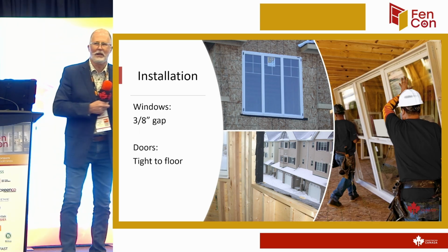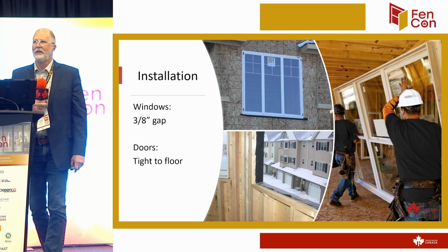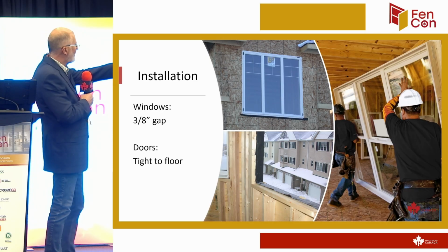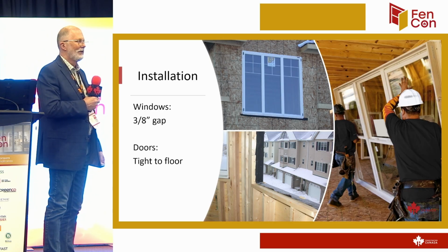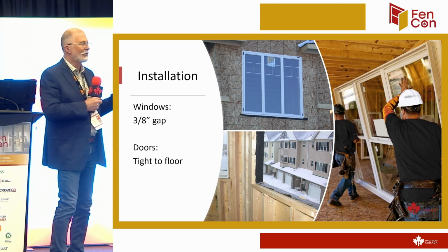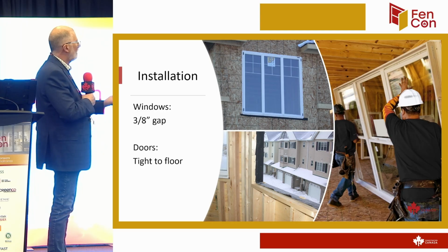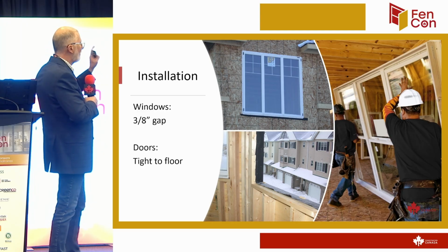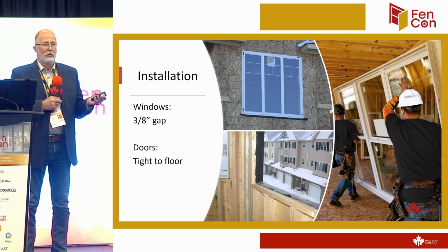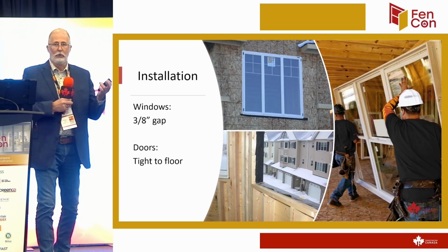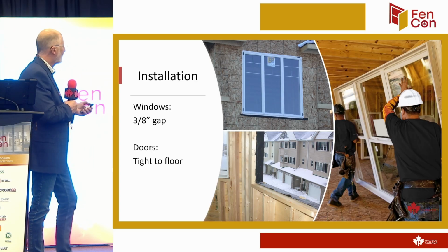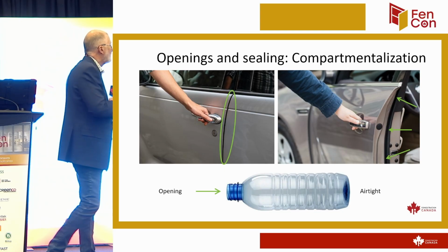Like, this is probably going up to about 10 years ago. And in fact, if I drive out to Ottawa and drive around in Ottawa, this is typically probably what I'll see. Instead of tar paper, I'll see house wrap, right? No protection really whatsoever when it comes to the rough opening. So we're installing these big windows. We're spending a fortune on windows. The window isn't going to be affected by the moisture. Like, vinyl doesn't rot, but the wood wall will. So the deterioration is in the actual structure. So that's where the risk is all being handled.